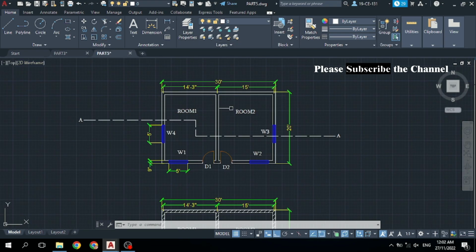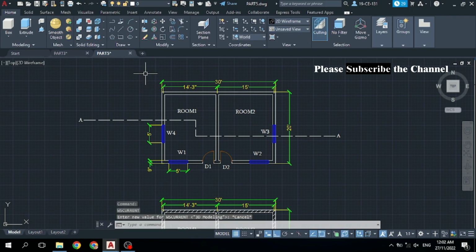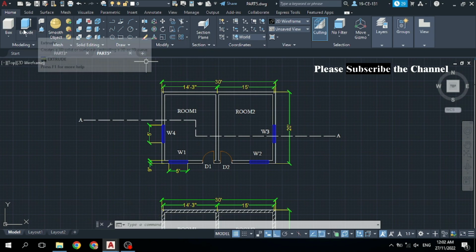First of all, I would like to prepare this display for 3D working. Now you can see it is all 2D commands. For that, simply come to this right down corner. You can see this workspace switching, this setting symbol, and simply click on it and select 3D modeling. Now you can see all 3D commands are available here. I will use the extrude and press pull commands for this 3D.